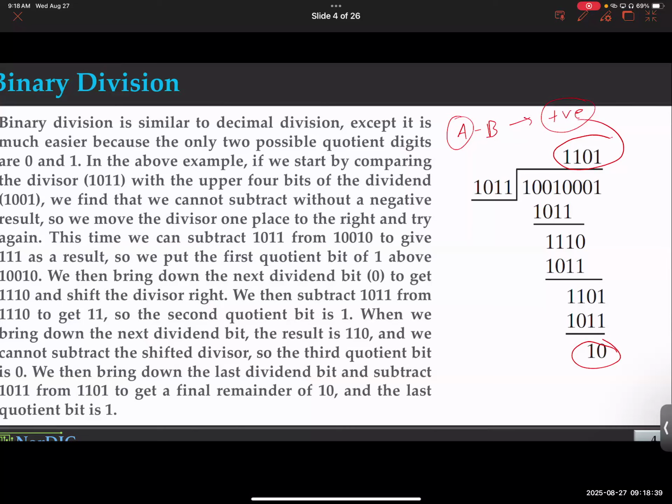And then we use that subtractor, which is basically deeper down, nothing but an adder, to divide. Because that subtractor, once you subtract two numbers, you look at just one bit, which is the sign bit. If the sign bit shows positive, it's positive. Remember the sign bit concept? The leftmost bit is the sign bit. So you just compare the leftmost bit and see whether it's 0 or 1 and figure out which number was bigger or smaller. And you just choose 0 and 1 accordingly. Does that make sense, folks?